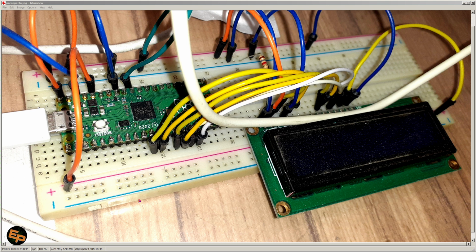If we power this device from a switch mode power supply, which is basically the easiest and cheapest way, especially since these boards need 5 volts, and we can basically use any old phone charger or tablet charger, well then the accuracy of our ADC readings will be influenced by how smooth this power supply voltage is.